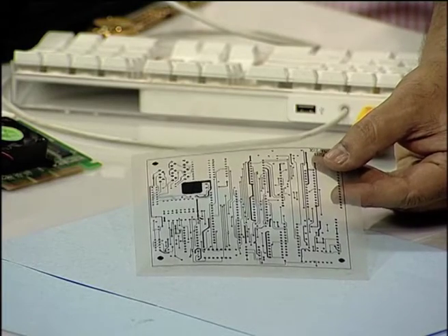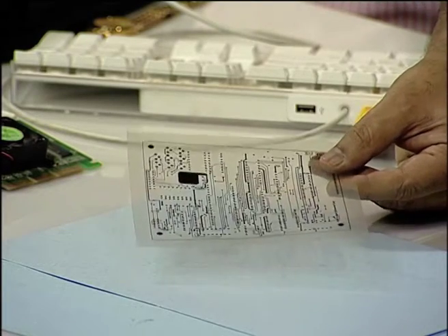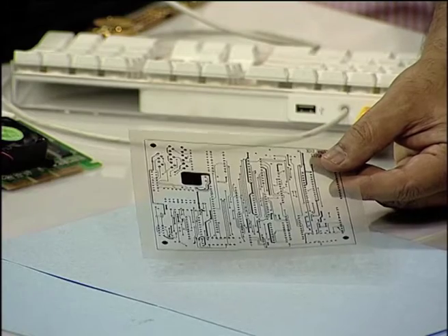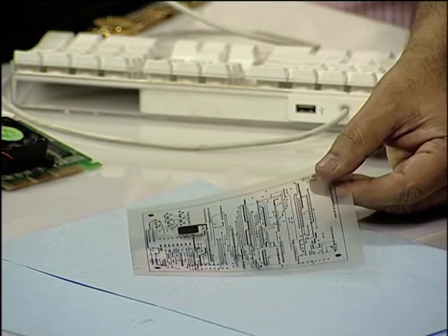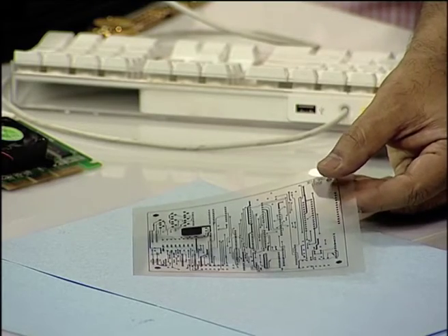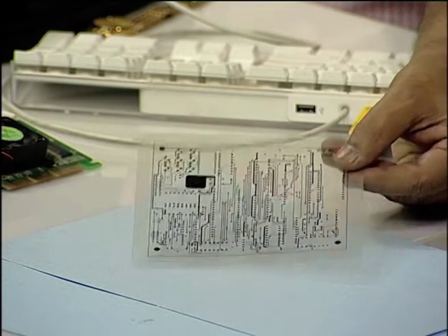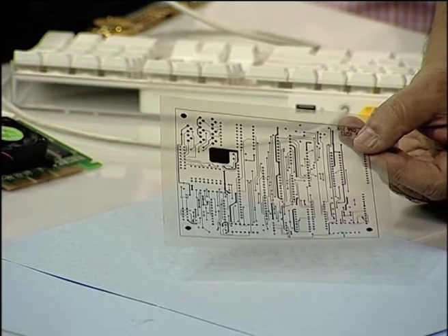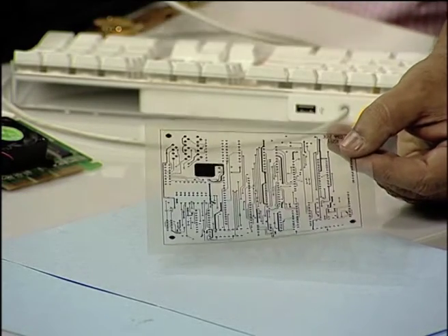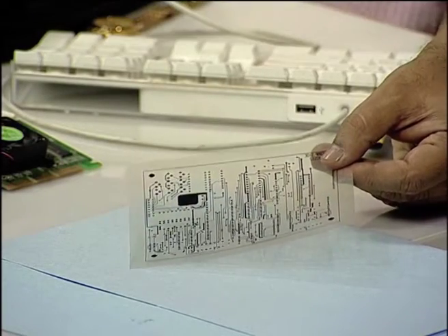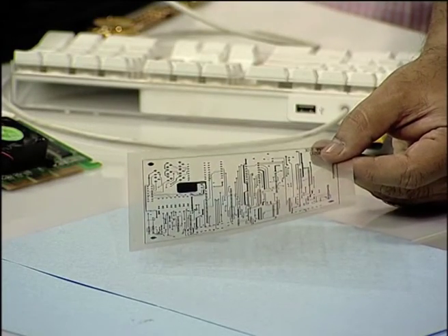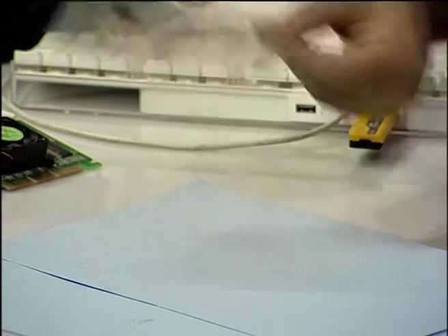So, if you have an 8-layer board, you will have 8 such electrical layer masks, in addition to the solder mask and the legend print for the top and bottom sides. So, this is a very precision process, and you can see it is a simple black and white contrast, but the black and white are of high contrast that provides better imaging once the process starts.